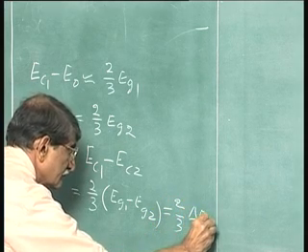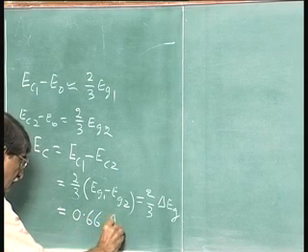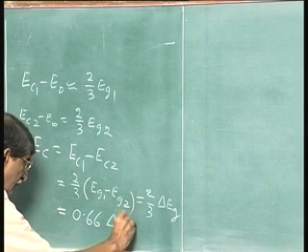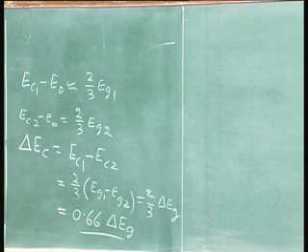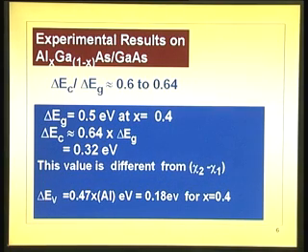All this has taken place because this layer is depleted. This is depleted, okay, and you have got this charge transfer taken place onto that side. And this is depleted, so it is bending down. This is depleted, so it is bending up. So, that is the thing that we have discussed.